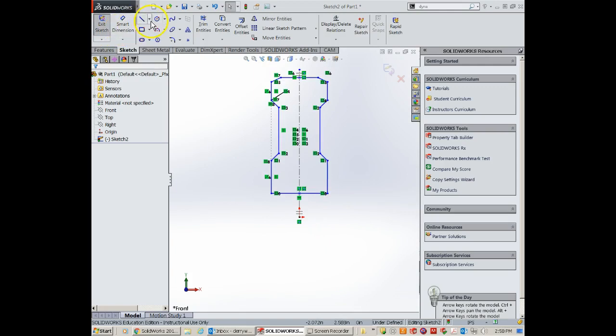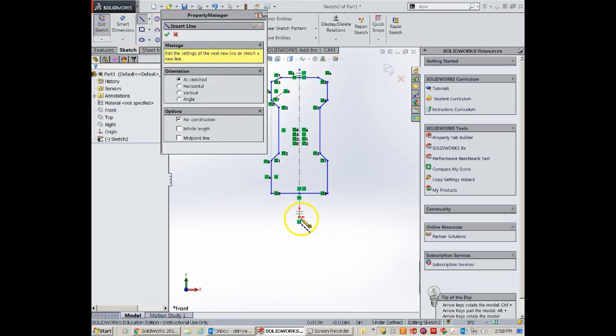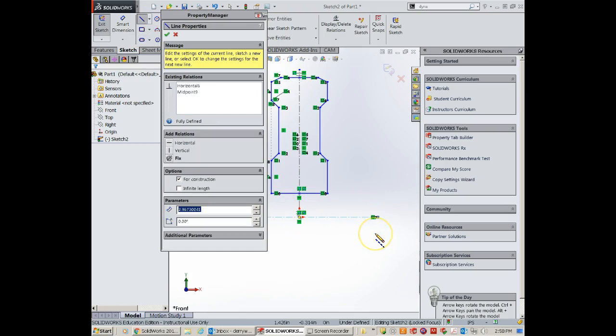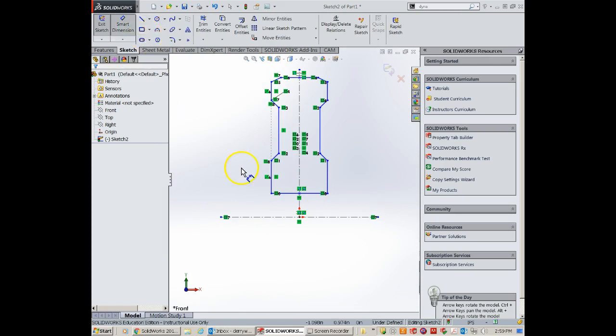They want to add a center line that we're going to use for our revolve down here. It's on the bottom of page 7-12. We're on to 7-13. We're going to add in these dimensions. Grab my dimension tool. Can start out with our width dimensions.